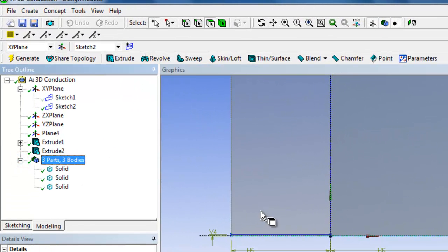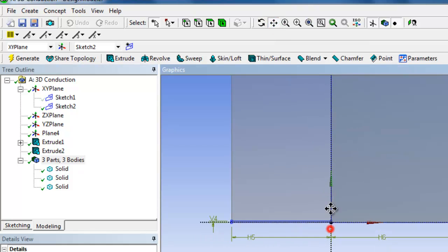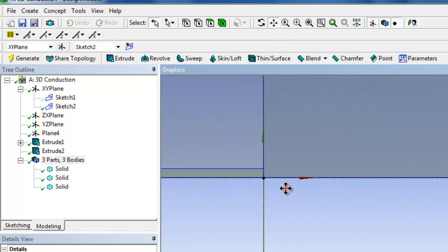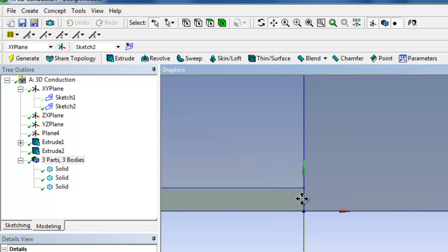When you have a separation in the sketch, as shown by this line right here, it will automatically create bodies that are separate from each other when you select Add Frozen. This is actually advantageous to what we want. It will help with our meshing in the future, and will help us separate the boundary conditions for the platinum. For only the bridge, only this micrometer bridge, will be producing heat and not the tab.